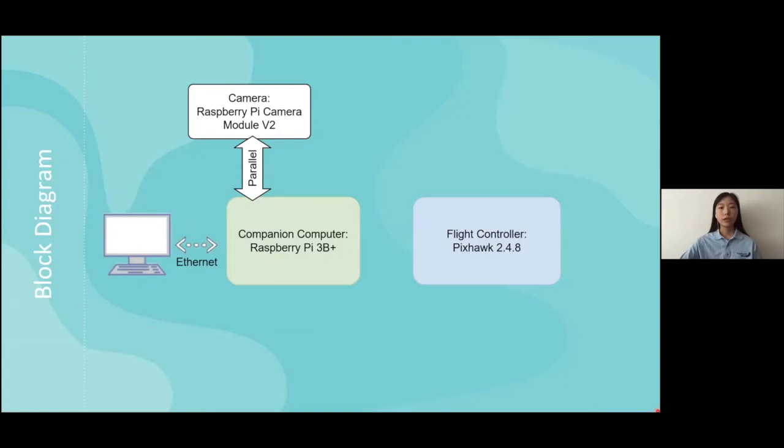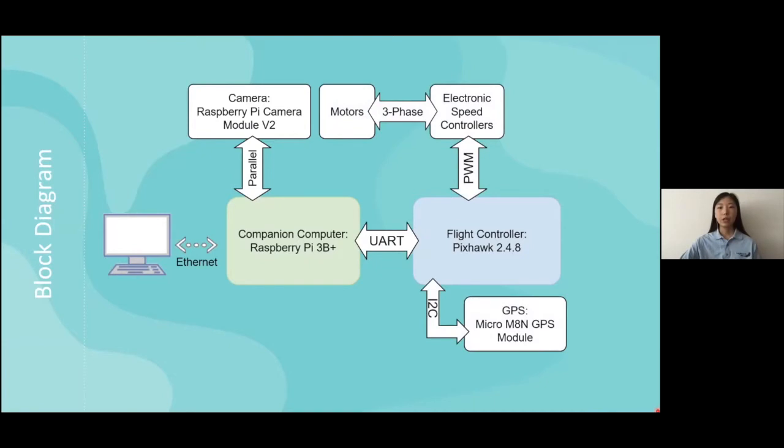To control the Raspberry Pi, we SSH log into the system using our own computers and type in the launch command. The coprocessor is VisHawk, which interfaces with the Raspberry Pi using UART transmitter and receiver. It ensures drone stability in flight. Motors make the propeller spin. Here we are using three-phase motors. Compared with single-phase motors, three-phase motors are more commonly used in industry, since their power is over 150% greater than that of a single-phase motor, and they are less noisy.